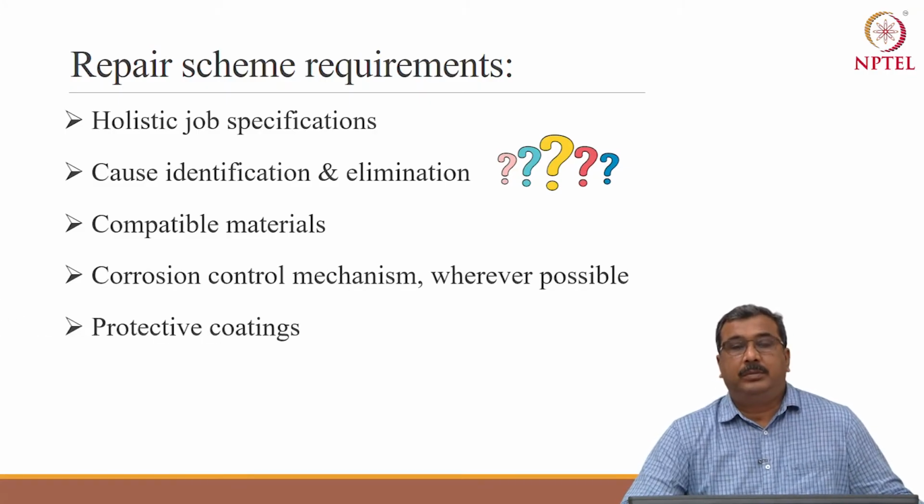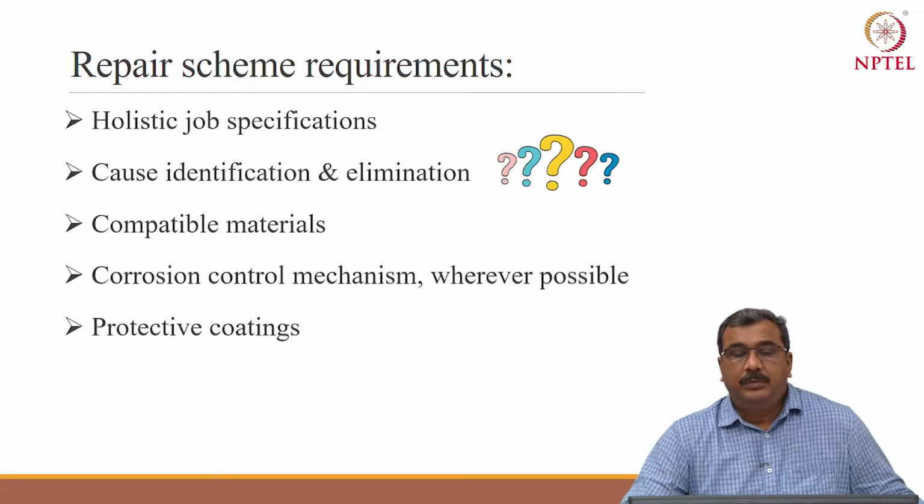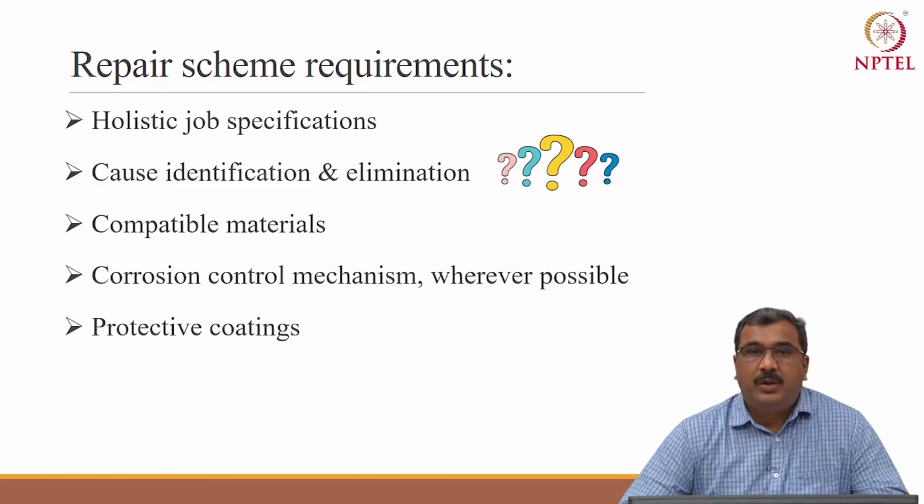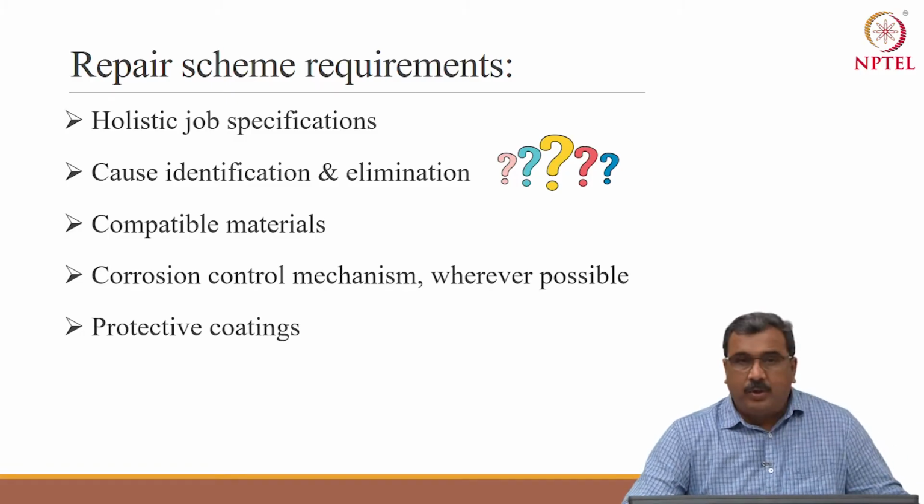Finally, protective coating. Type of coating, thickness of coating, and application methodology all have to be derived based on the site condition. You cannot have a non-aliphatic epoxy coating on the outside surface, or a simple anti-carbonation coating for a chemical resistance element. So, a protective coating has to be selected properly.